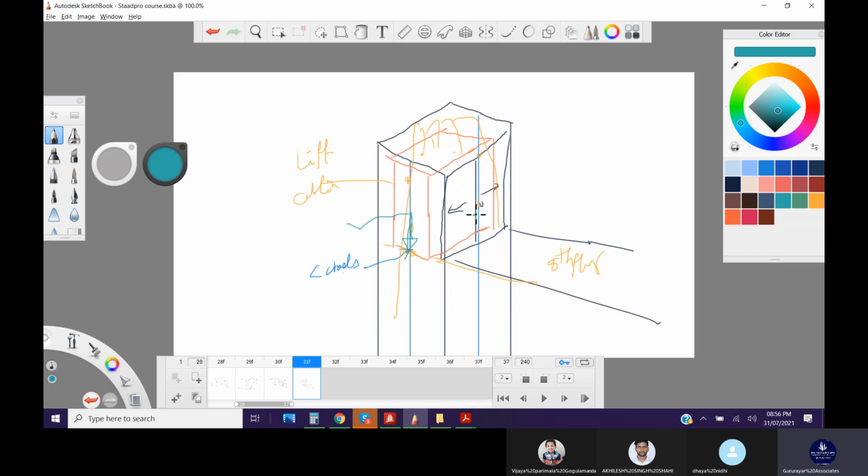So approximately, let's say at both joints, one joint and the other joint, maybe 2 kilonewton. This input will be given by the mechanical engineer, again the lift vendor. The lift vendor will provide how much reaction the cabin gives. So 2 kilonewton means around 200 kilogram here and 200 kilogram here. So it's a big load, 400 kilogram with the cabin, and with people also sometimes all together. Maybe 3 kilonewton or 4 kilonewton will be given by him, sometimes 5 kilonewton also, because it depends on the size of the lift. So approximately, we will take 2 kilonewton here for this exercise. For the future, we have to get this from the lift vendor.